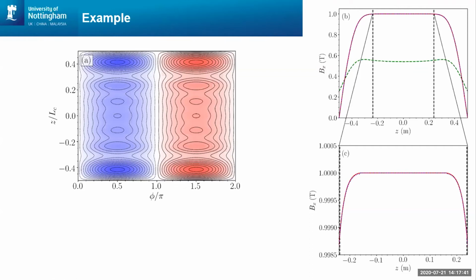We've also calculated it numerically using a finite element calculation in COMSOL with the magnetic shield treated as a perfect magnetic conductor, in dotted blue, and we've calculated it analytically with our model shown in red. So you can see in figure C that our model is fairly accurate, and it's actually accurate within 0.002% of the numerical simulation.